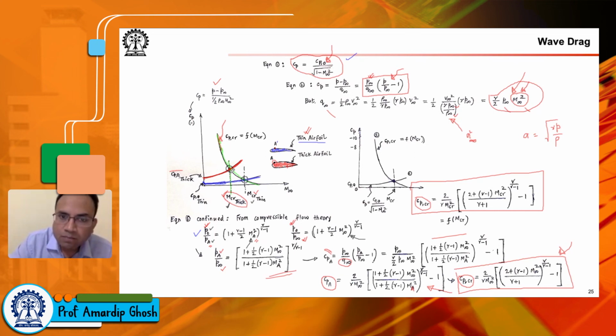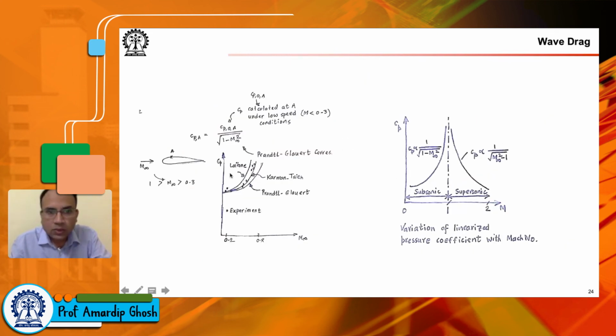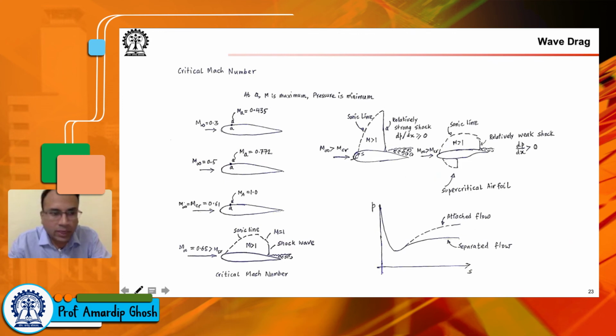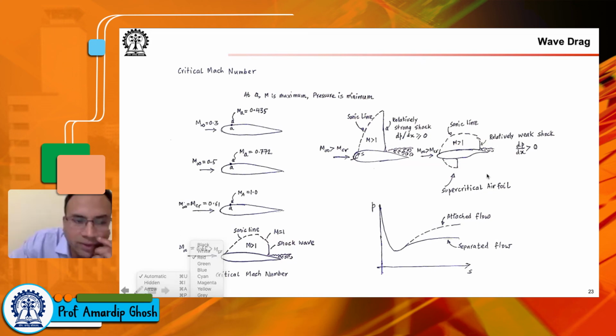But the problem is, as I said, the structural rigidity of the thin wing or thin airfoil cross section is a little tricky, and also sometimes if we use the wing for storing fuel, a thin airfoil doesn't serve our purpose too well. So for that, we use this supercritical airfoil. So it's still a thick airfoil. It's almost like the airfoils that we have seen for low-speed vehicles.